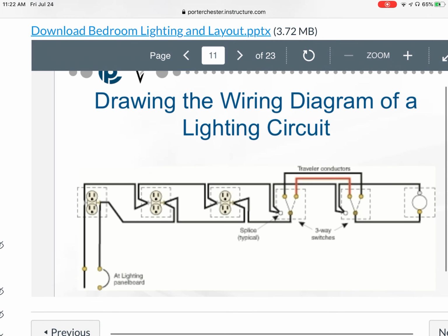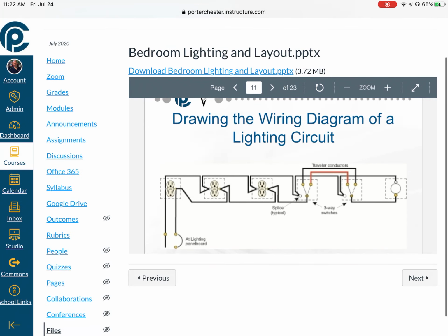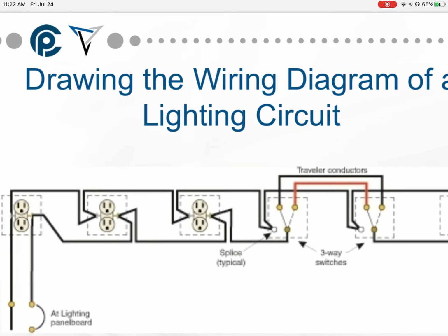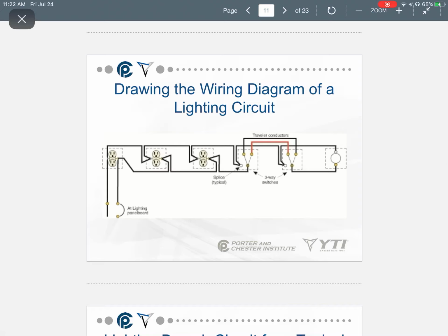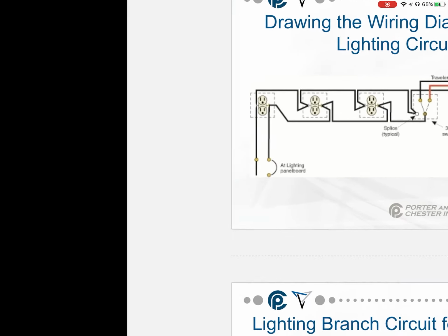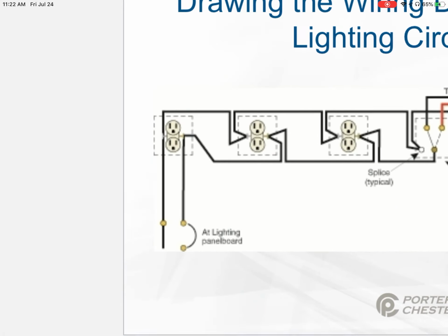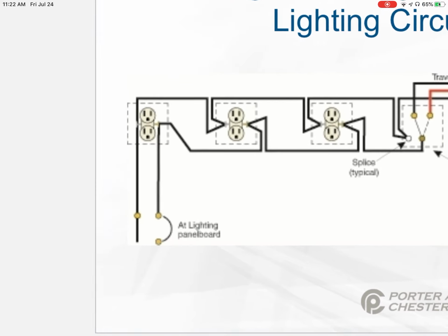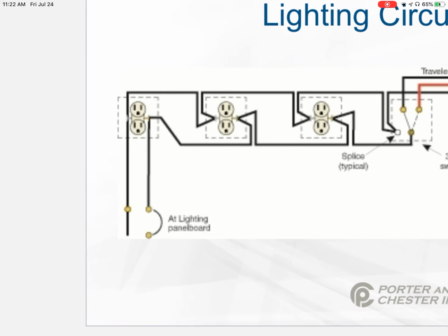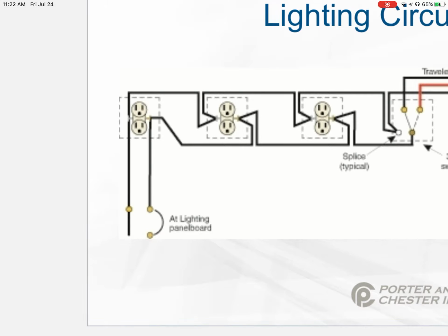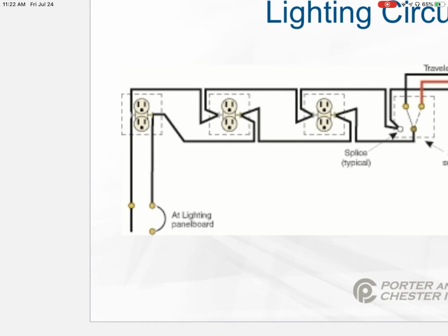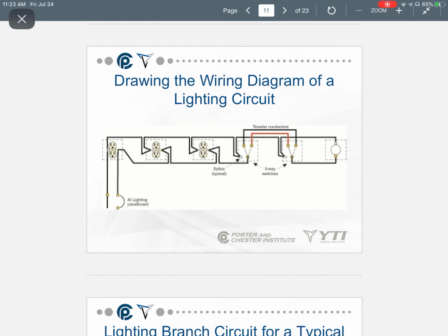All right, let's take a look here, guys. This is a good illustration. All right, so first of all, I want to start here on the left side of this drawing down here. This little symbol with the curved line and the two little terminals, that's your breaker. That's the universal symbol for a breaker. And then to the left of that, you see this line on the outside. That's our neutral connection. So you see the neutral connection going along, basically in and out of each device.